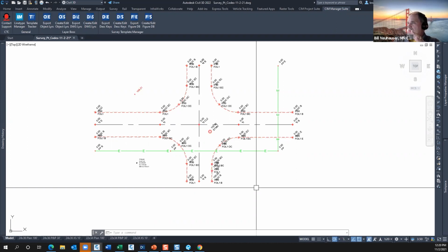Okay, we're going to have all of our symbols turned on. We're going to have our manhole symbols, our power poles, all the stuff we can stumble over and break a foot over, right? Okay, that's all going to have to be turned on. But as far as our points are concerned, not all of them are going to be turned on for the topo. Typically speaking, we turn off everything except for our symbols, correct?